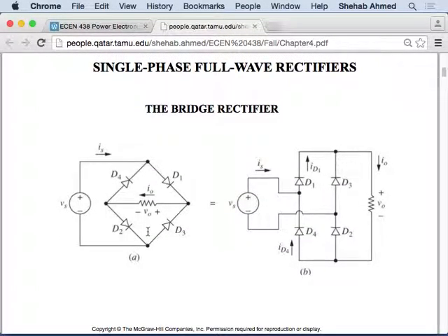I think we will go through in a similar fashion. So we'll go through the equations, I mean, all the waveforms first. You feel comfortable with those, and the equations are pretty much identical to what we had before because the current waveform is exactly the same, right? As soon as you have an RL circuit, you impose a voltage across an RL circuit, you will still see the same shape of current rise and then fall based on the time constant. So that's why nothing changes really. The only things that change are really the waveforms and the circuits. But the equations for current will be very similar, right? So the most important thing is to be able to understand the waveforms for the different circuits.